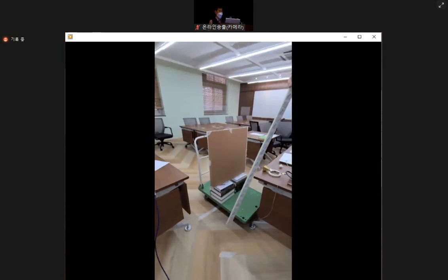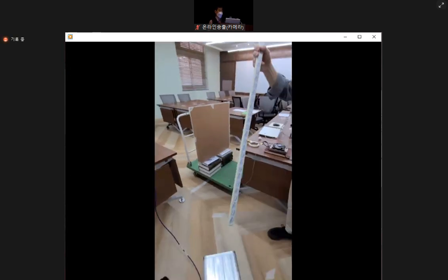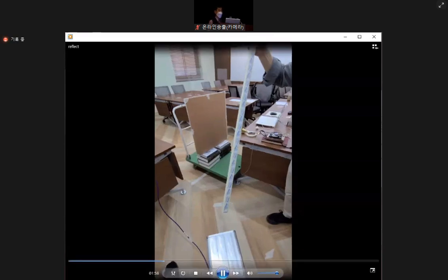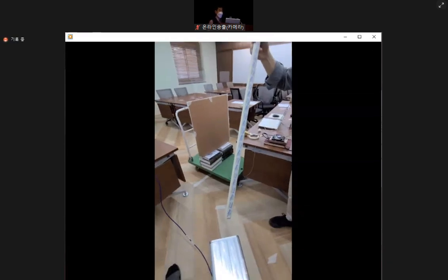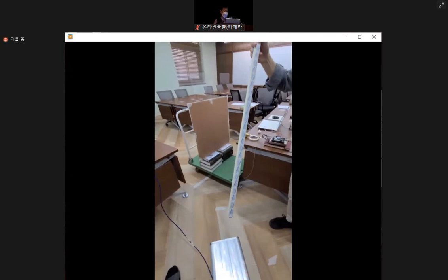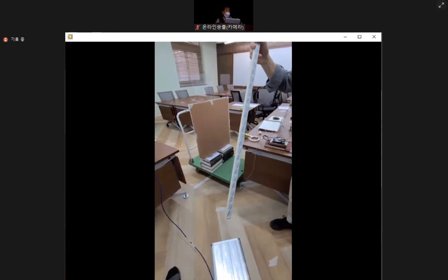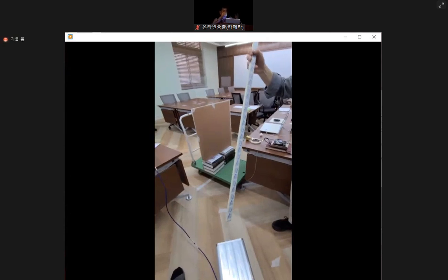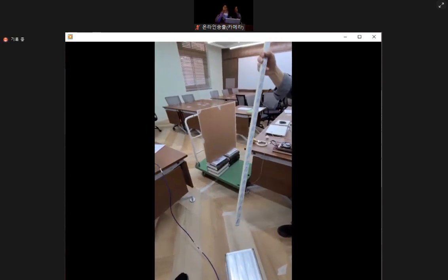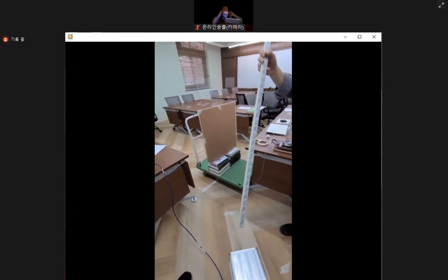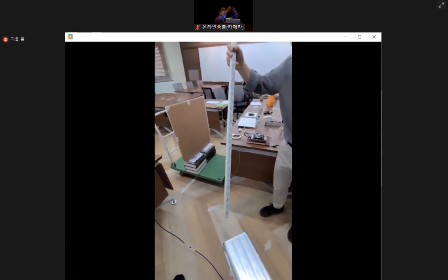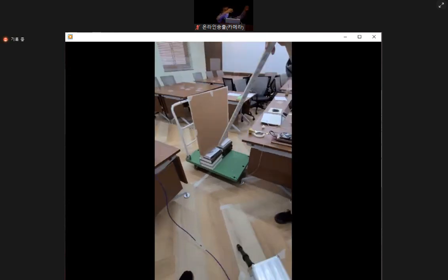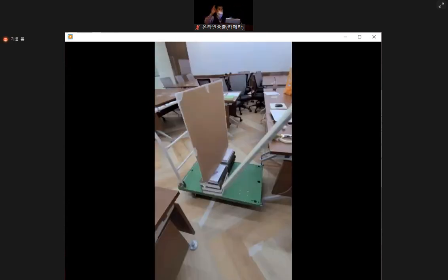The reason I had to change the position of the probe farther from the metamaterial surface, if you see, this is the best angular position targeted by the metasurface we designed, and we will move the angular position starting from 45 degrees to an upper angle of reflection and a lower angle of reflection, and compare them.